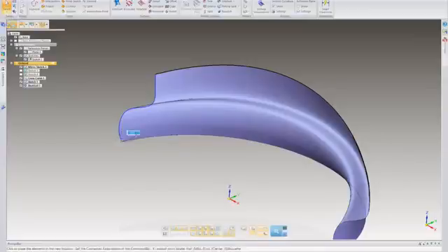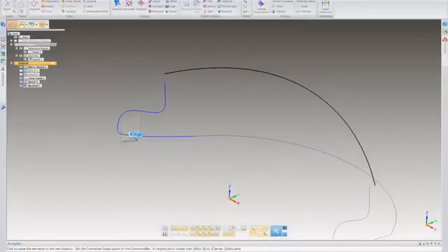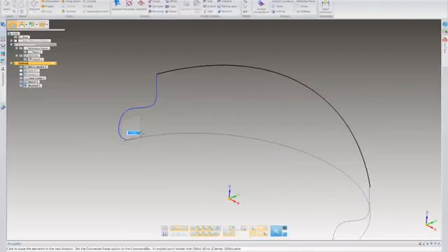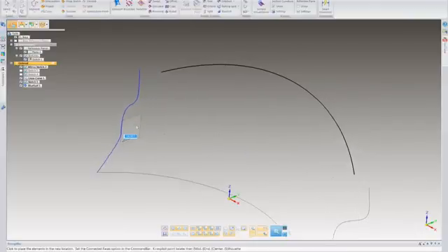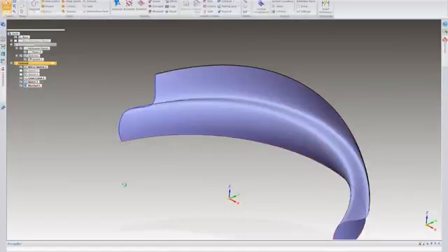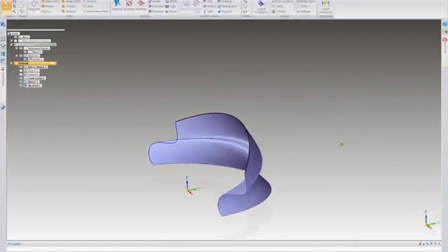So let's try taking this and moving it in another orientation. And let's try rotating it. Oh, as you can see, some of the sketches disconnected. That's probably the way I created them. I didn't actually connect those top sketches to maintain there. So my 3D curve is kind of falling off, but you can see as I drag this around, the bottom sketches and everything else kind of relocate to it. All right, so that is some of the functionality that you would get by doing both in one environment.